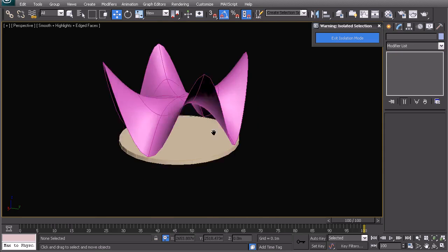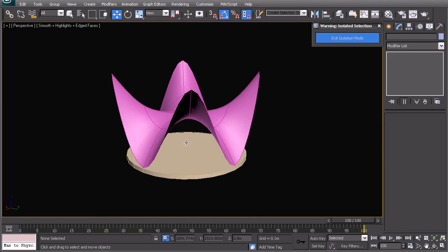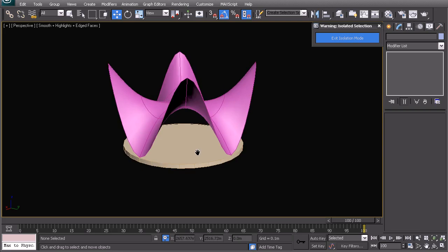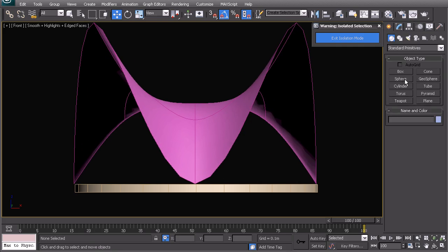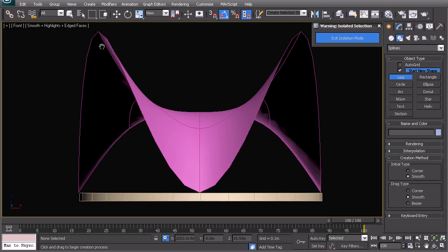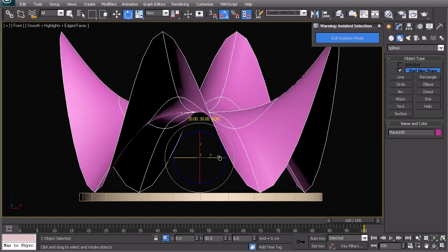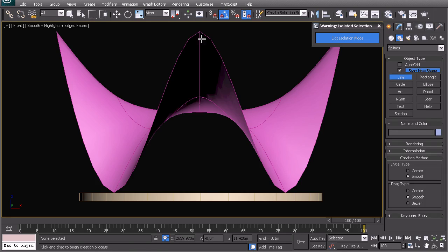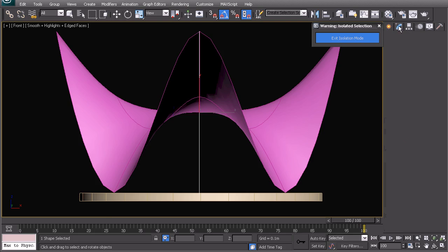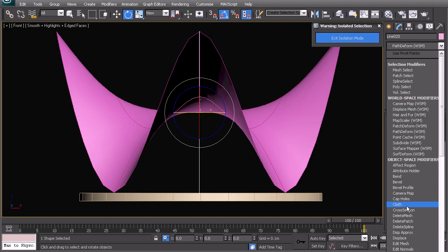Now if we want to make it look more realistic, we can add some prop-up poles on the 4 sides. So we're quickly going to do that. We'll start in the elevation, and we're going to add a line. Let's turn this by 45 degrees, and it's just going to allow us to work exactly in line with what we're creating. I'm holding down the shift key just to make a straight line, and I'm going to sweep that.